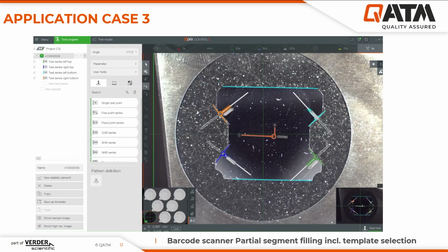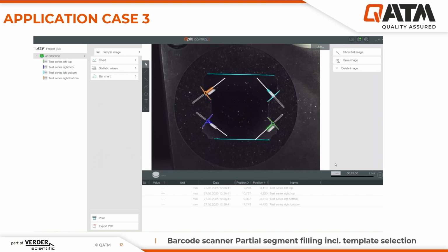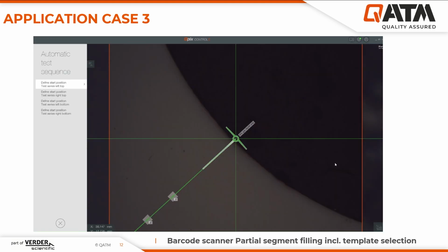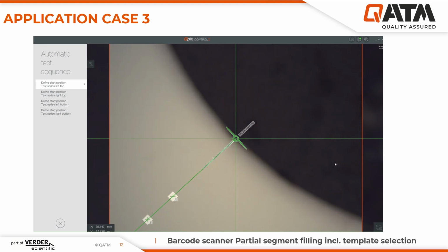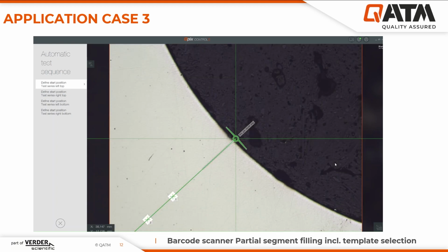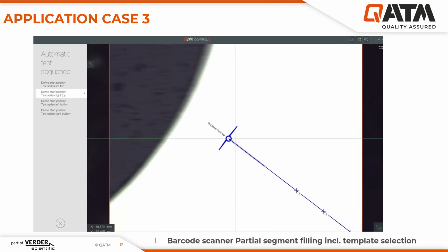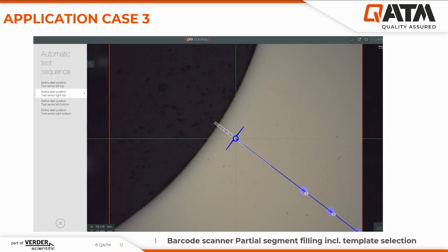and we also get rid of the manual check because we're using, in a highly efficient way, the edge detection function. The software is automatically moving to every single position, adjusts the position individually, knows the contrast of the resin and the sample, and adjusts it 100% to the edge of the sample.